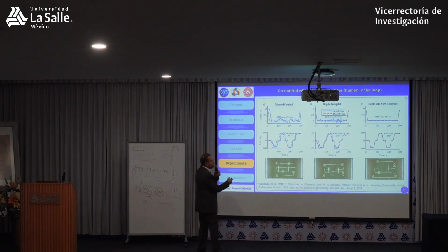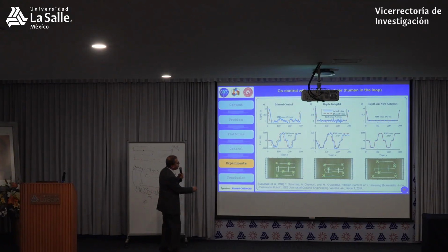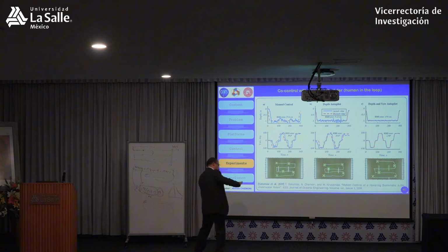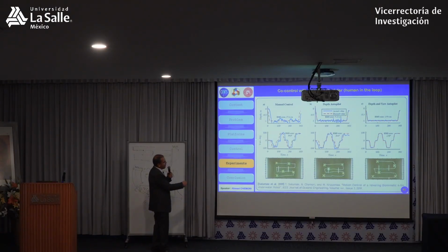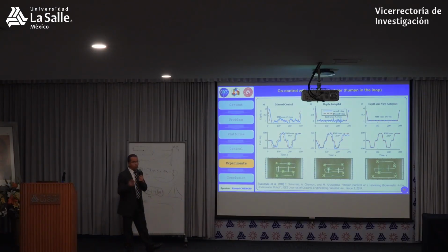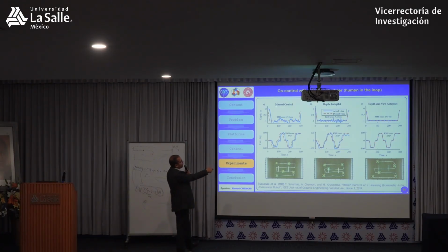Fully manual, the human will control 3 degrees of freedom. He should go until the desired depth of 1 meter. And he should keep this depth constant. Keep the vehicle at this depth. And he should control here the yaw angle. Move like that, turn, move like that to follow this trajectory. And then, so he controls the depth, the yaw, and also the surge, X. And this is to obtain the result for fully manual.